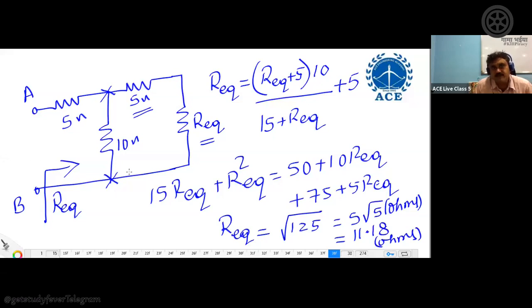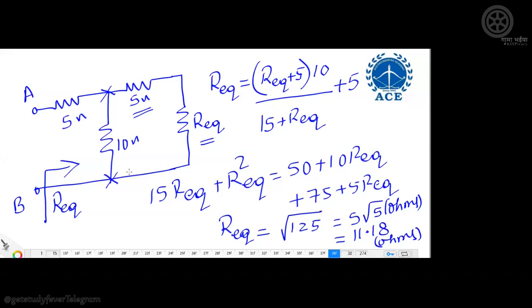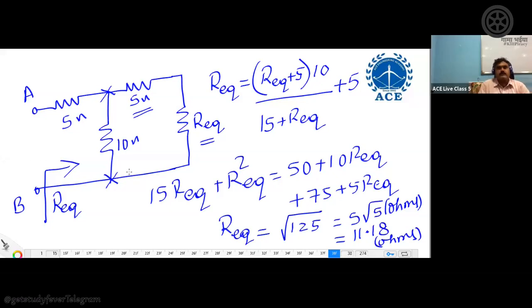If it is a step waveform, no problem. You square the amplitude, you will get it. Like a step voltage of 5 volts is there. Square will be 25 volts. That's all. But if it is a line equation like T, square means it becomes T square. Okay. Means you cannot square the amplitude for ramp waveforms. You have to take the line equation and square it. Okay.